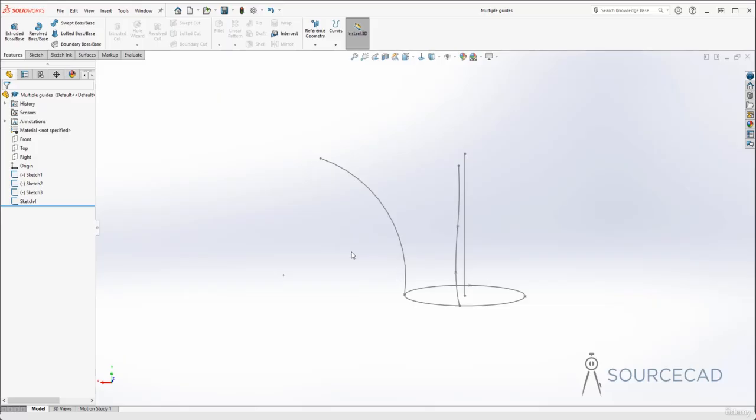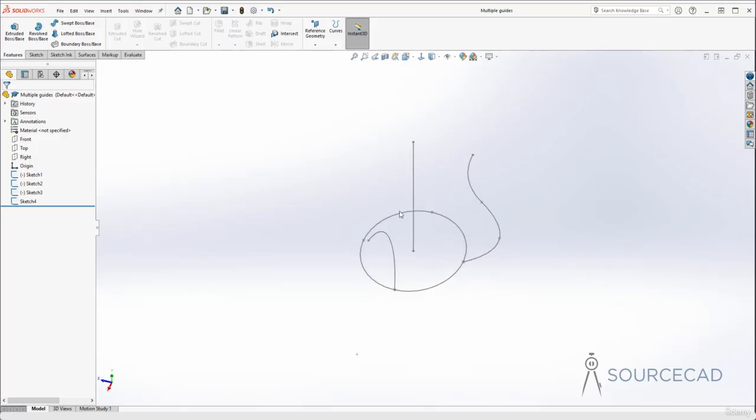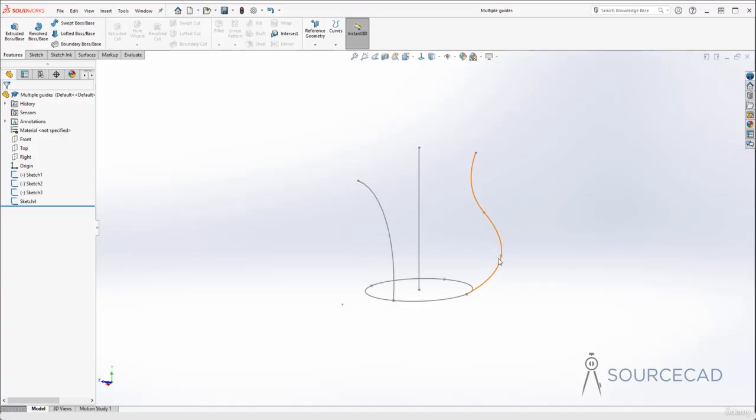This one is made with an arc and this one is made with a spline, and this thing is an ellipse. It's not a circle, obviously, because if you use a circle here, the 3D geometry will fail, because in this case the diameter is changing here and also here. So diameters are changing in both the directions, which is not possible for a circle. A circle cannot keep up with these kind of changing shapes.